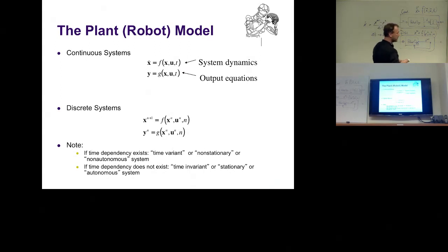And it's a good approximation. So it's very easy from just 2 time steps to get velocities by numerical differentiation. There's other states which are much, much harder to estimate. For instance, if you have a humanoid robot and you want to know the orientation of what is called the base coordinate system, let's call it the butt in this case, it means where is the base coordinate system in space, in a 3D world, and what orientation does it have?